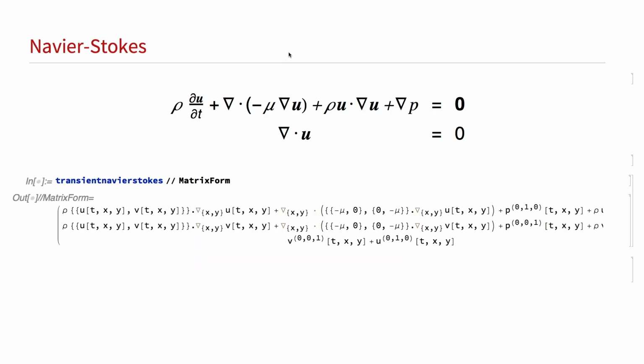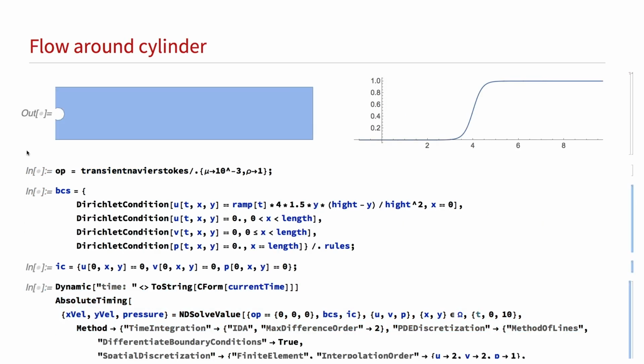Right. Transient Navier-Stokes. So now, same Navier-Stokes equation as before, now stuff is time dependent. So this is an inflow box. The box, for some reason, should extend further to around here. The cylinder here is slightly off central, and it should actually be more in the middle of the box. I don't know. And there's an inflow profile coming from the left. So the flow is surrounding the cylinder. We're going to ramp up this inflow profile with this type of ramp. So after about 2 seconds, the inflow is going to slowly come up.